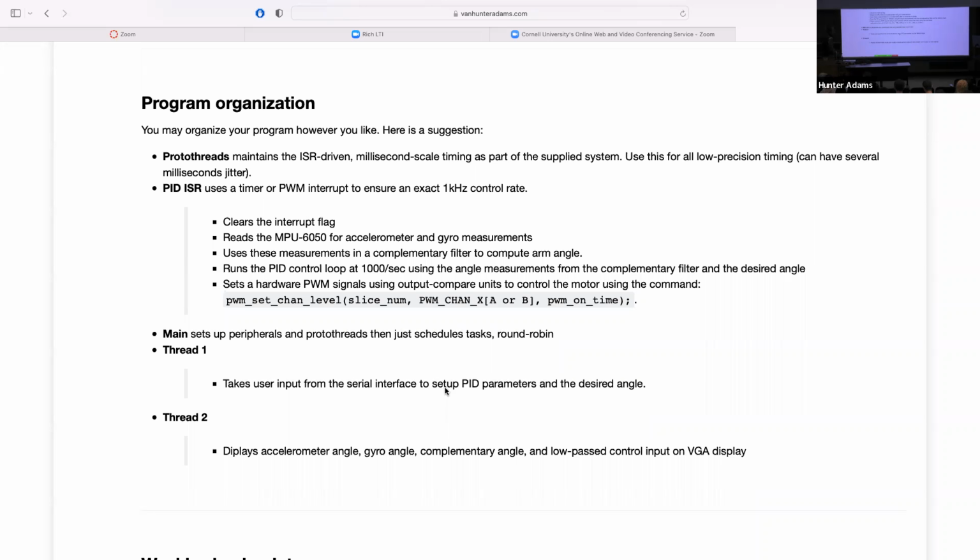So on some architectures, it may be the case that you would want to be careful about modifying the PWM duty cycle asynchronously from the PWM channel, because on some architectures, that introduces a glitch on the output for one cycle of the PWM channel. But remember from our conversation a few lectures ago that on the RP2040, those two registers that control the PWM channel's period and duty cycle, in particular the top register and the CC register, which stands for counter compare register, are double buffered.